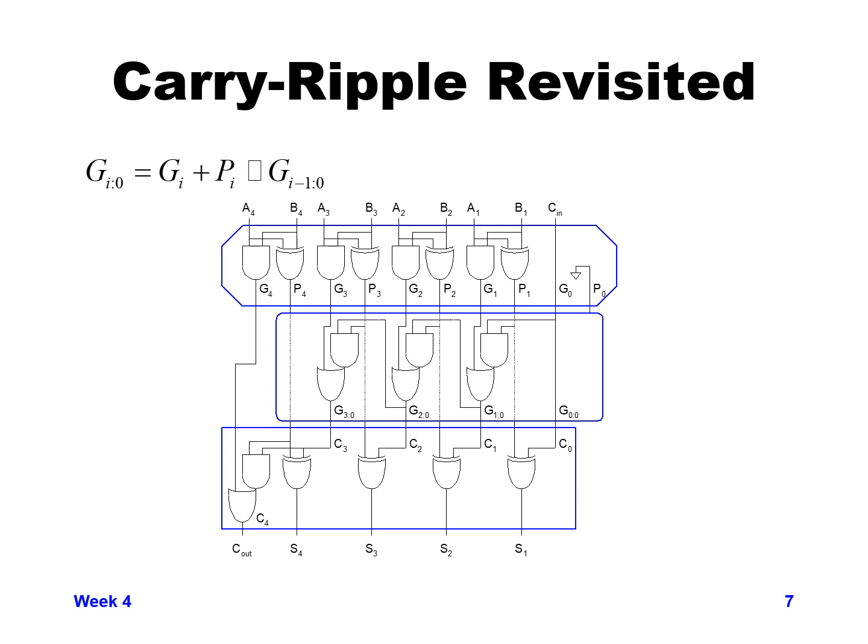That G sub 1 colon 0 is now our carry sub 1 coming out of this PG functionality, but it also goes on to the next bit in order to help calculate G2 colon 0. You can see again the equation for G2 colon 0 is G sub 2 ORed with the combination of ANDing P sub 2 with G sub 1 colon 0.